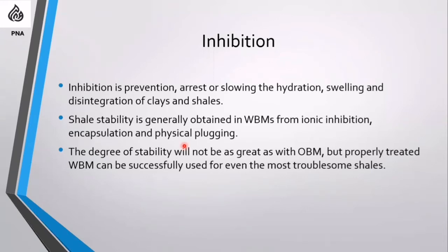The degree of stability in water-based mud is not as great as with OBM, but properly treated water-based mud can be used successfully to drill the troublesome shales without any problem if we treat it properly and our properties are as programmed.